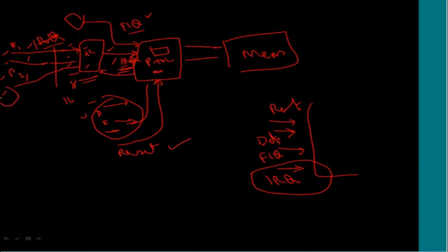Individually, you may wonder what are the different peripherals that are possible. There is a UART, and a USB controller could be there. UART is a serial controller, and then different disks can be connected to this. Timers can be connected. So these peripherals can be connected to this, and the interrupt controller will prioritize them, and then they will generate an interrupt to the processor.